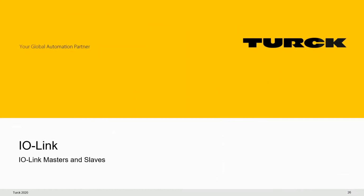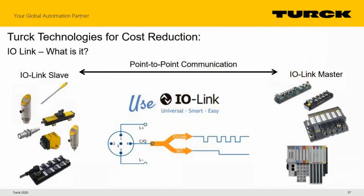So IO Link is a topic. It's a great topic for cost reduction. If you're not familiar with IO Link, it is a point-to-point communication. It is considered a sensor bus as opposed to a field bus because it is point-to-point. And it is an IO Link master on, we'll say, the PLC side, and an IO Link slave device on the sensor side.